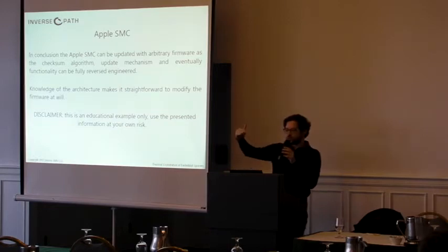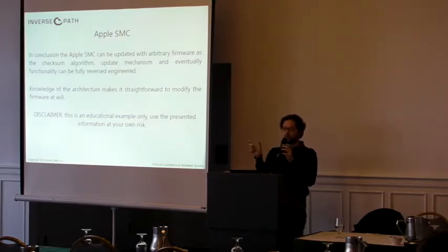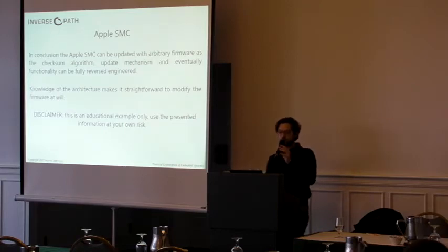So there are some tools that will apply 60 different algorithms, and they will start doing it at different offsets at the top and at the end, and they will try to understand and to exclude where the checksum is. Also because usually you have your checksum somewhere, usually it's at the bottom, but that might not always be the case. And if you include that in your attempt, then you will always fail.